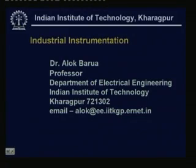Welcome to lesson 24 of industrial instrumentation. In these lessons, we will consider piezoelectric sensors. As you know, piezoelectric sensors are based on piezoelectric crystals. They have a property that if you apply a force across the surface of these crystals, I will get a voltage, and this process is reversible. That means if I apply a voltage, I will get a force also.